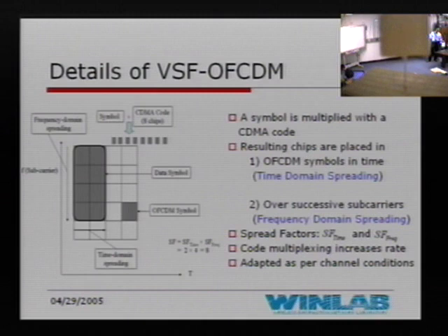I think you're right that in terms of signaling there is no difference, but the choice of spreading sequence is what makes the difference in his case. No, they do the same. They can, because he will adjust this two-dimensional spreading sequence. So here I have the option to adjust the dimensions according to the channel characteristics. Well, they could also adapt. Probably that's not a fundamental difference. Yeah, in principle. But in deployed multi-carrier CDMA systems, at least the impression I have is they put different symbols in different subcarriers and do spreading along each subcarrier. Whereas here it's a very adaptive factor. That's why we have this variable spread factor, the first part of the name.